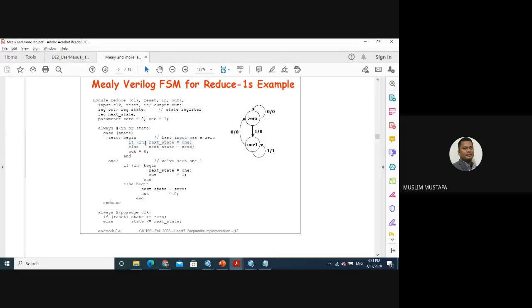So if the input is equal to 1101, then go to the next state, then the output is 1. Check it again here. If the input is still 1101, then you set it high. If it's not 1101, else begin go to state 0. So it's exactly the same, we just change the input here.